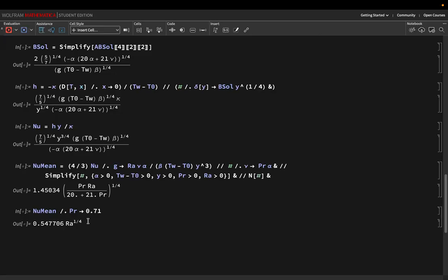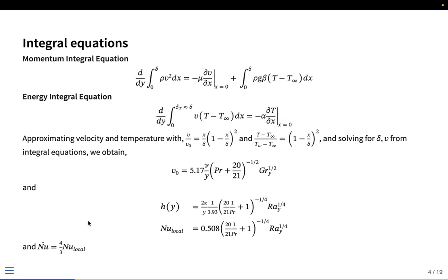And as it is pointed out, even in the forced convection cases, this particular technique, the integral solution method, will give you an answer, but you do not have any way to verify whether your answer is correct or not unless you compare it with experiments, because there is no theoretical basis as to why this particular assumption is better or worse than any other assumption of profile that you could possibly take. Since we do not know that beforehand, all we are saying is that if you assume this, this is the value of Nusselt number you're going to get.